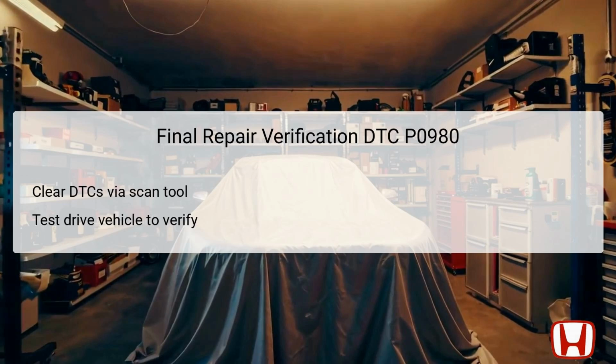After completing the necessary repairs to address DTC P0980, it is imperative to verify that the repair was successful. This verification process begins by clearing any diagnostic trouble codes using a scan tool. Once the codes have been cleared, take the vehicle for a test drive to observe whether any new codes arise or if the AT gear position indicator resumes normal functionality. Performing a test drive is essential, as it allows for monitoring the transmission's performance under real-world conditions. If the malfunction indicator lamp, MIL, does not illuminate and the transmission shifts smoothly, this indicates that the repairs have likely resolved the issue. If the MIL reactivates or performance issues persist, further investigation will be necessary to ensure that the root problem has been fully addressed.